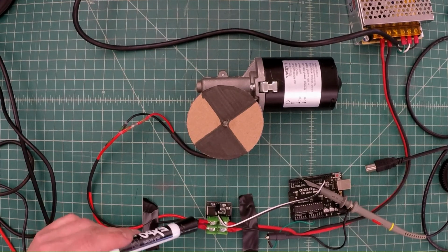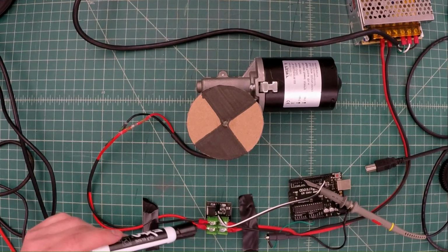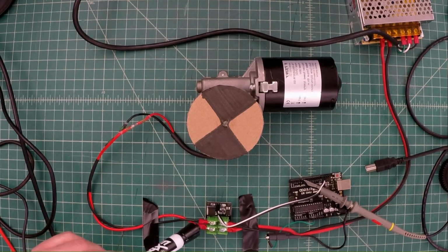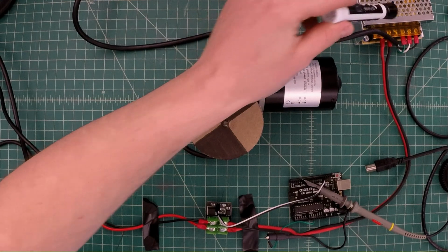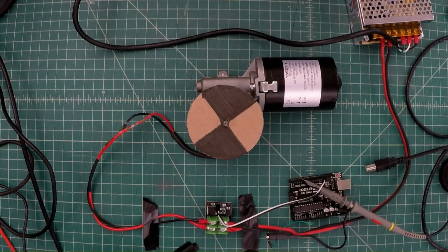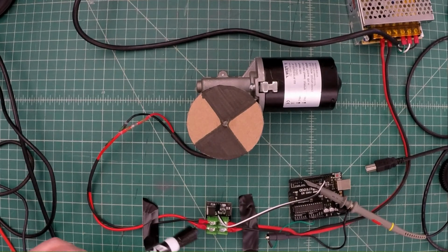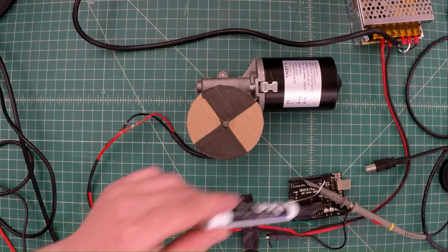Okay, so the transistor is, again, our switch that we're going to be rapidly flipping on and off to control the speed of this motor. So coming into the transistor through these leads here, we have our 12 volt power supply. So this plugs into the wall and it produces 12 volt direct current that will be switching on and off with the transistor. Also attached to the transistor are these two leads right here, which lead back to the Arduino.